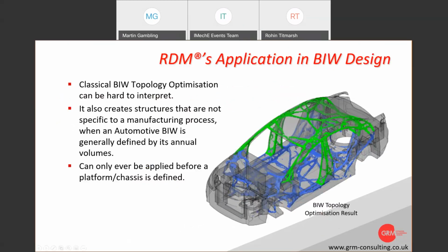I guess a bit of reason as to why this process has come about, what we would want to use it for, is topology optimization. Hopefully, those of you attending have come across it. It's becoming much more popular with the advent of generative design inside CAD systems. But really, it's starting from a design envelope, a big package volume, setting your requirements for stiffness or vibration or whatever, and then developing the idealized load paths. And that, as you can see, is great. It gives us this scheme for the best layout of a car.